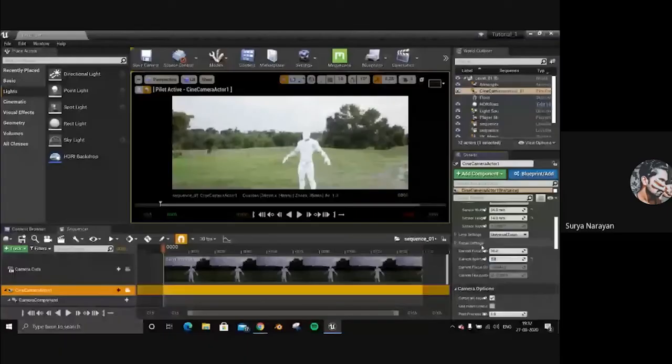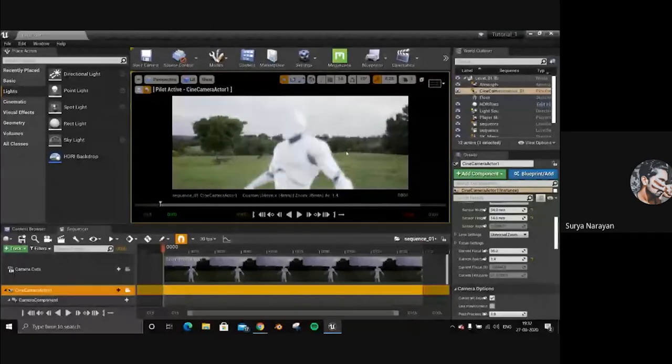If we move down, we go to the current aperture. Let's change that to 1.4. Now you see the mannequin is a little bit blurry. It's not focused. We'll fix it. So we have done all of that. Now what you want to do is place your camera in a way where you want the shot to be taken. I'm just going to place it right here.